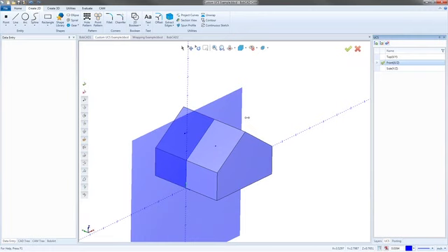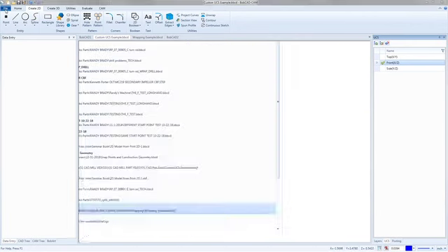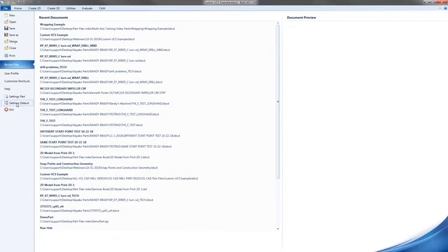But one problem that I have, it's not really a complaint. It just depends on the monitor. I've found a lot of it to be how well you actually see that plane. On my laptop, it's really dark, even on the same settings that I have inside my BobCAD here. So to lighten it up, if you ever need to, just because you really don't need to see the whole thing all the time, you can go up to File, and then either Settings Part or Settings Default. Settings Default, remember, is going to affect this every time. So in this case, the Settings Default would allow me to make changes to every file that I do after this, but it will not affect the window I'm currently on.